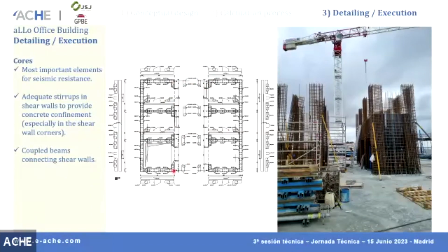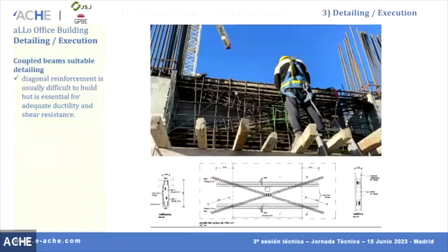We had others, but this was the lift. And we have some beams connecting these two shear walls, and there were coupled beams that had large shear forces and bending moments, and they must be properly detailed.